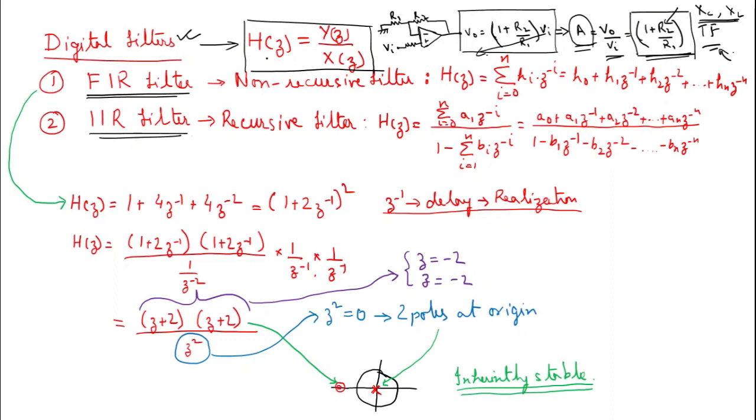So, what is this H(z)? H(z) is nothing but a function which is varying with frequency, because when we talk about the z plane, we have this z operator, which is nothing but a complex operator wherein the frequency is related with the z. Okay, digital frequency is related with the z. So in other words, we can say H(z) is dependent on the frequency component. So if you see, what is V0? V0 is the output, so that is Y(z), and Vin is the input, and hence we have the X(z) component over here. So H(z) is equal to Y(z) by X(z), output by input, okay, in the complex domain, right?